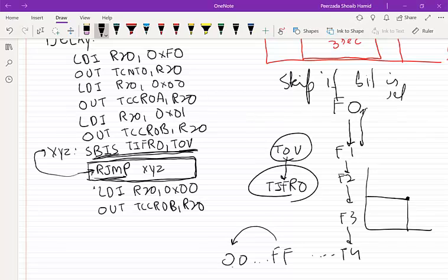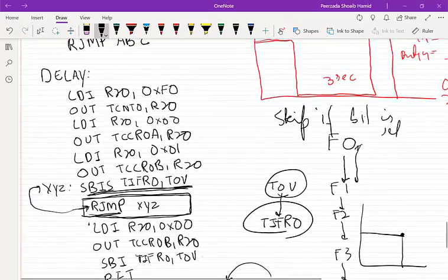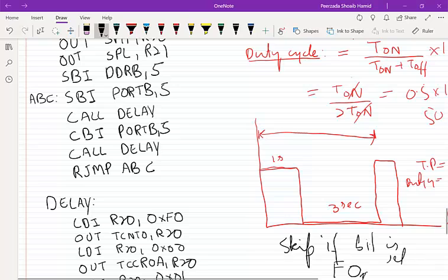and after that I will simply clear also the timer overflow flag so that this timer will be used once again. TIFR0 timer overflow flag, and I will return to the original program. I will return to the original program here, clear the bit, that means it will go 0 now. It was 1, that end will go 0.